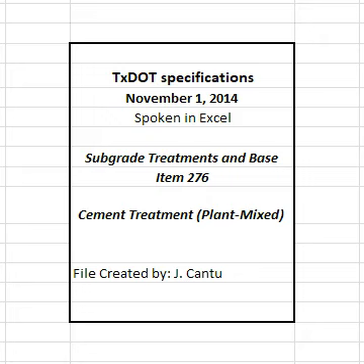2.5 Mix design. Using the materials proposed for the project, the engineer will determine the target cement content and optimum moisture content necessary to produce a stabilized mixture meeting the strength requirements shown in Table 1 for the class specified on the plans. The mix will be designed in accordance with TEX 120E. The contractor may propose a mix design developed in accordance with TEX 120E. The engineer will use TEX 120E to verify the contractor's proposed mix design before acceptance.